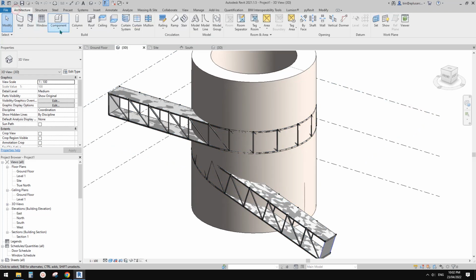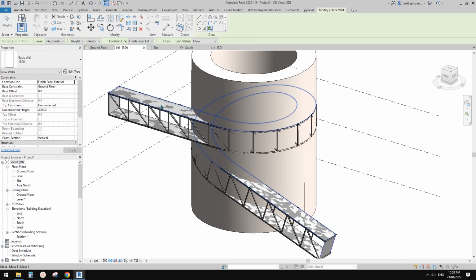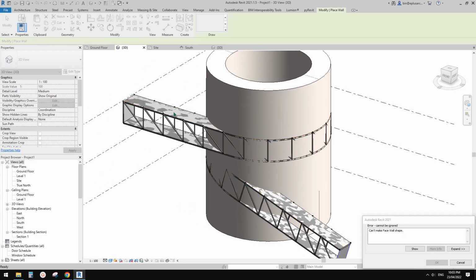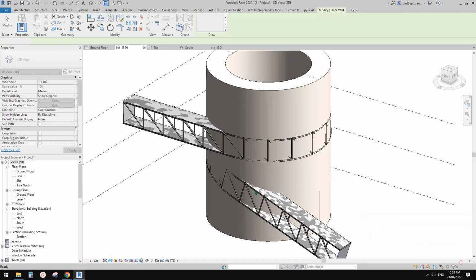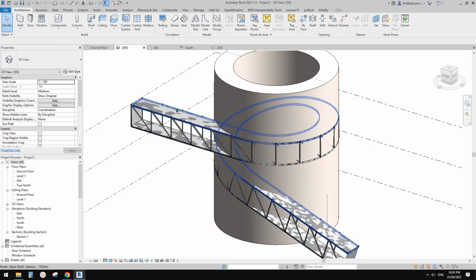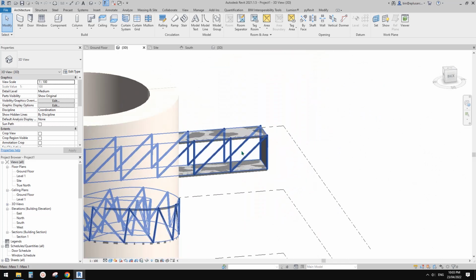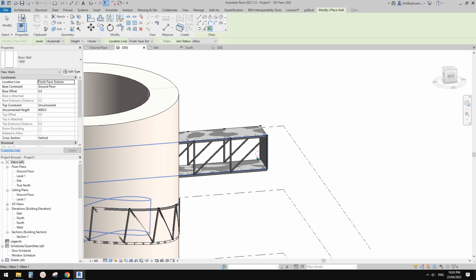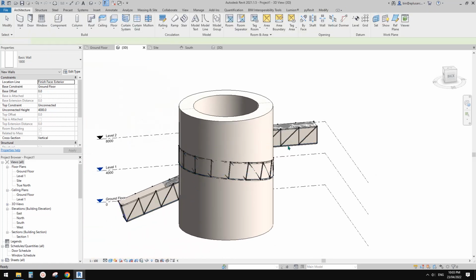So let's create a wall by face. I'm going to pick the top of this. Okay, pick this one. So now you will see we have this wall. Oh, hang on. Can't make face wall shape. Doesn't work. That's okay. So maybe let's try the side of this massing. Wall again, pick this side. Okay, so this time it works.